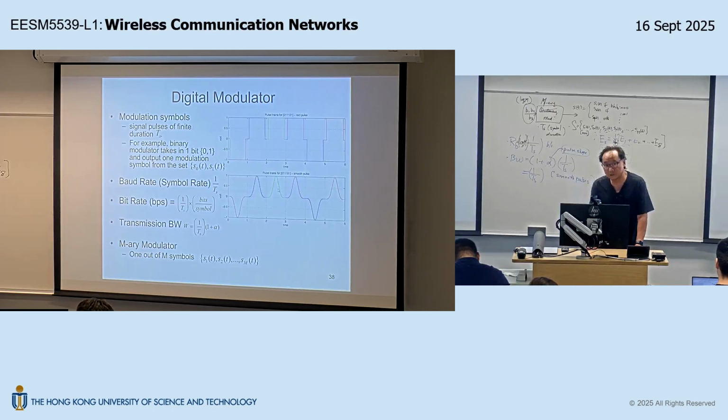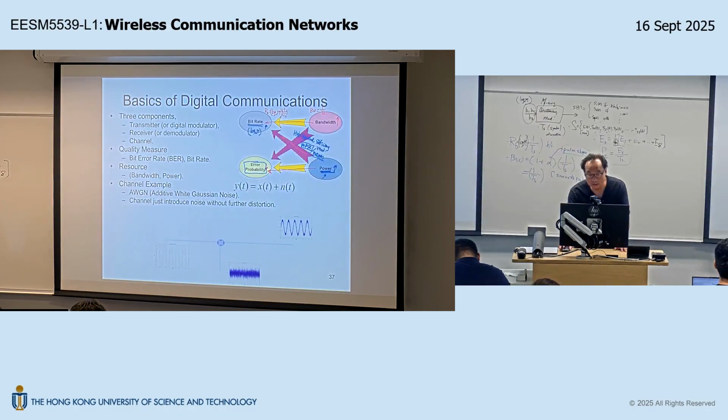The hidden cost is because you have this illusion, simply because we haven't talked about the bit error rate yet. And we are not ready to talk about bit error rate because we haven't talked about the receiver. Obviously, bit error rate depends on the receiver. But after we talk about the receiver and then the bit error rate, you will have the overall, holistic picture. By then, you will see that the penalty of just increasing M this way would be higher error probability.